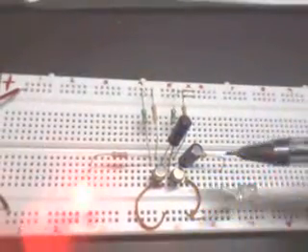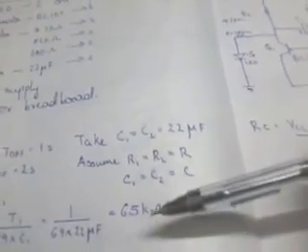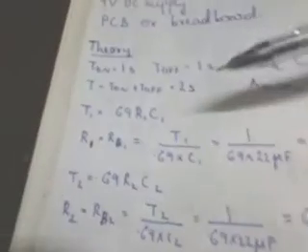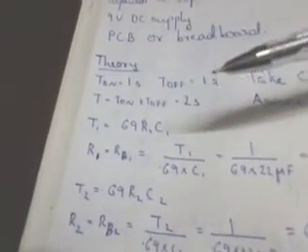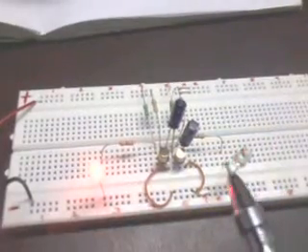So now the time period is 1 second, and you can decrease or increase the time period based on this RC resistor and this capacitance that you can see over here. So now I have assumed 22 microfarad. Now if you change the value of the capacitor, you will need a much smaller or bigger resistor. You can make the time period 1 second or 0.5 seconds or 0.001 second as you wish, so that the Astable multivibrator makes transitions faster, that is from one stable state to another stable state. We can increase the stable state time by varying the value of capacitors and resistors.